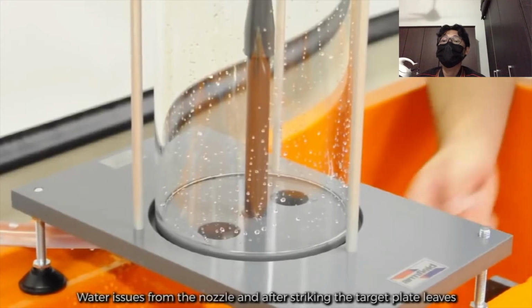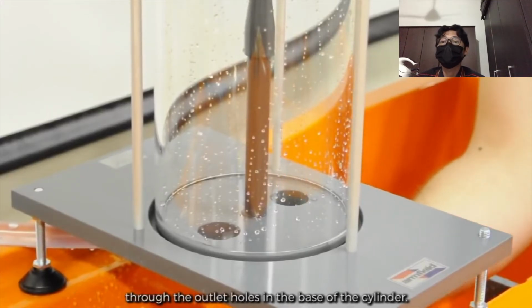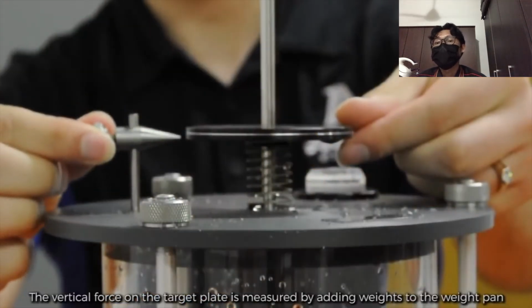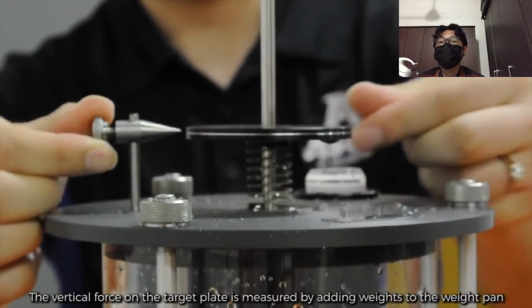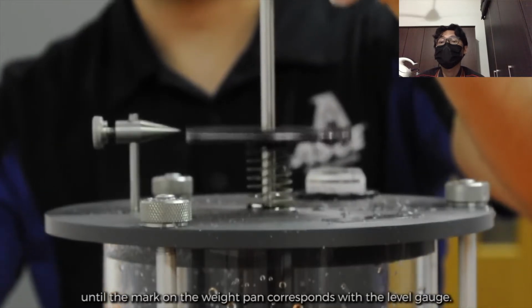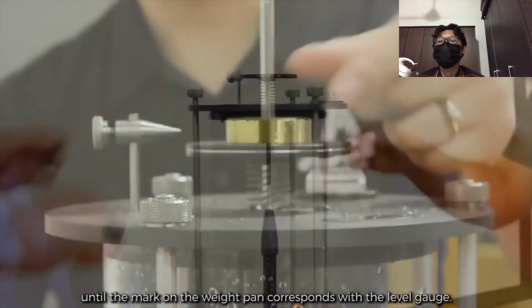Water issues from the nozzle and after striking the target plate leaves through the outlet holes in the base of the cylinder. The vertical force on the target plate is measured by adding weight to the weight pan until the mark on the weight pan corresponds with the level gauge.